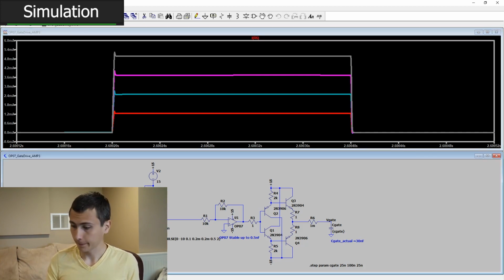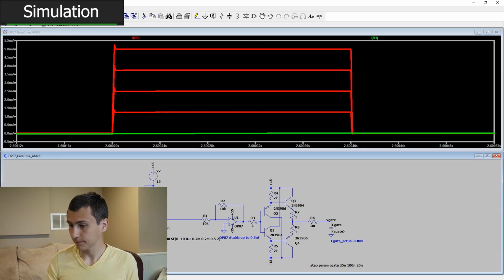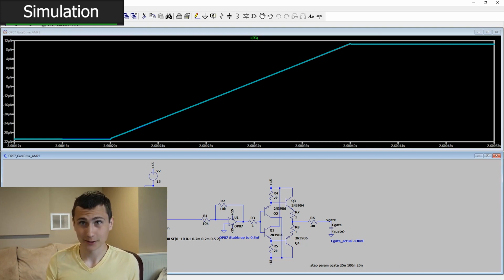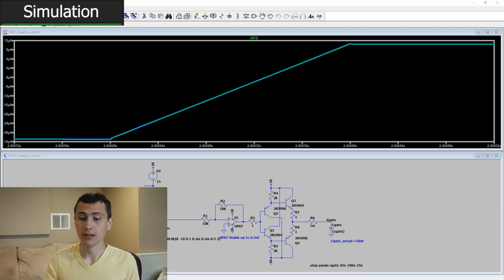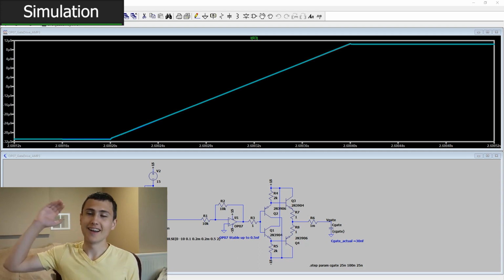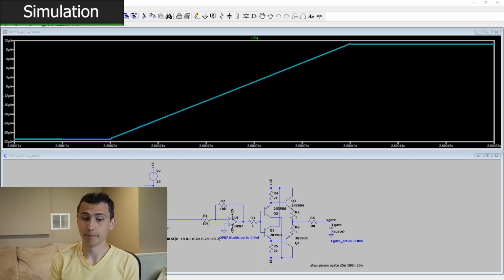But more importantly, if we look at the current out of our MOSFET, we can see that it's microamps. There's almost no current flowing into those BJTs, as we would expect, as we would desire. If there's no significant current coming out of our OpAmp, that's confirming that it has basically no part in charging and discharging that capacitor. That's coming from the much beefier discrete BJTs. In other words, one could say that adding the discrete BJT voltage follower just absolutely annihilated the effect of gate charge and gate capacitance for this OpAmp in this system. Basically, heck yeah, let's keep this moving forward.